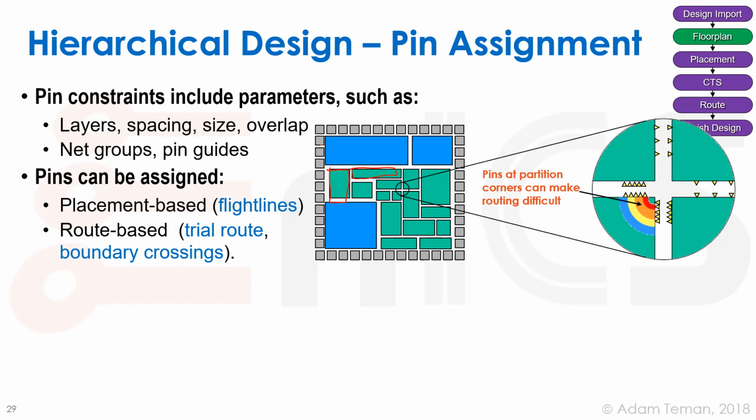There are two ways. If we're doing bottom-up design, for instance, if we made a macro that we're going to reuse in several places, then we arbitrarily, or according to where we want our modules to be placed, scatter the pins in a certain area. But that's not very good, because that puts a constraint on our higher level.